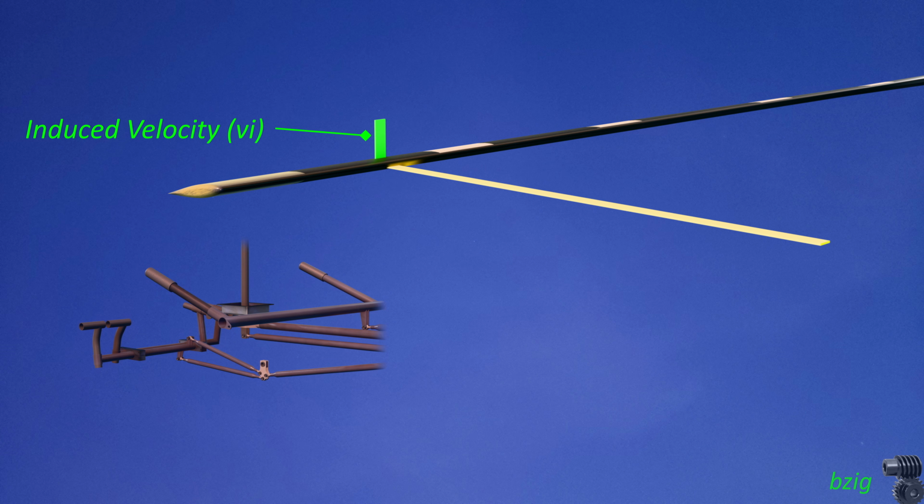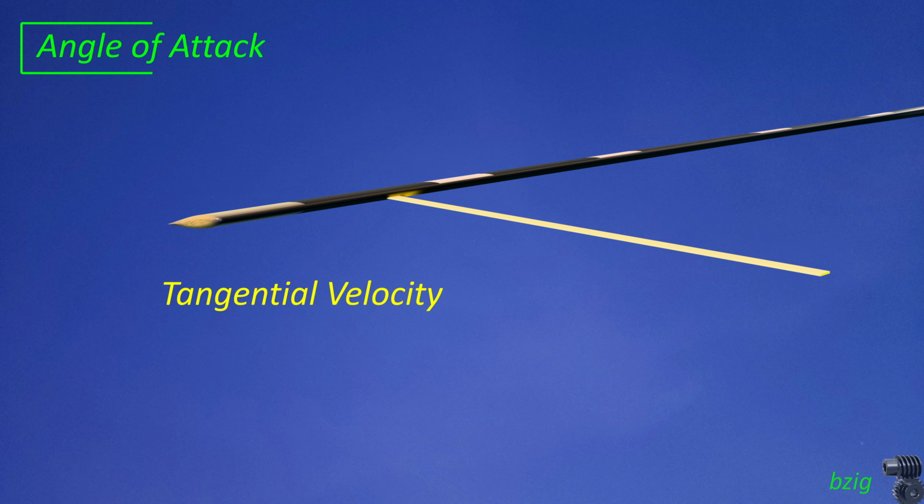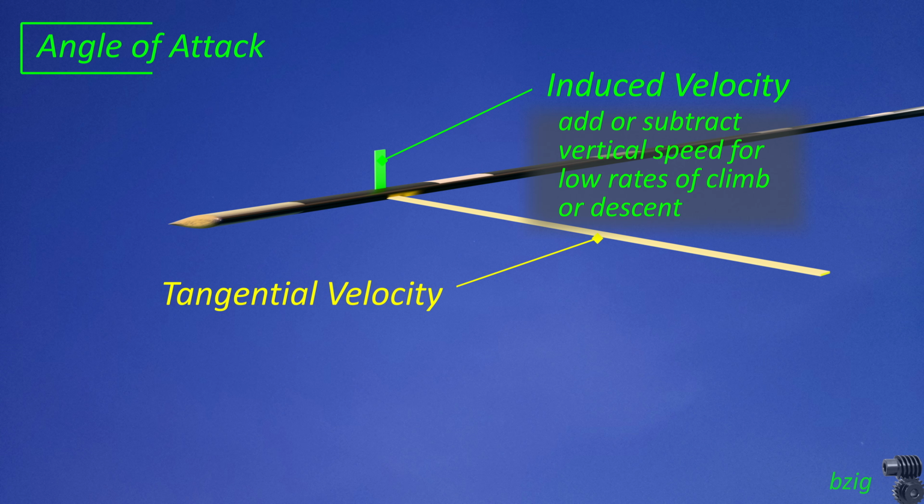We now know for any radial position along the blade, the tangential velocity caused by rotation, the induced velocity through the disc, and if the helicopter is climbing or descending, we can also add the vertical speed to the induced flow. But a comment here, momentum theory only gives meaningful results at low vertical speeds.